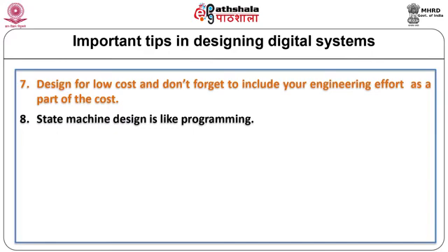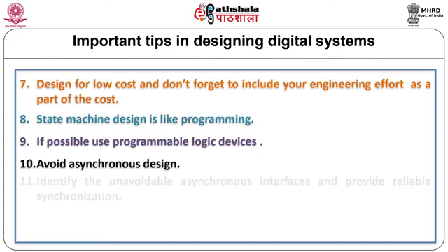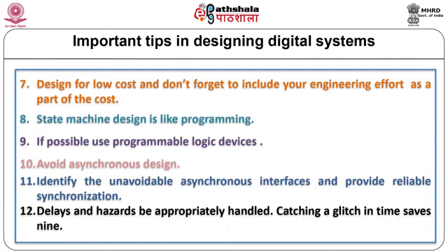State machine design is like programming. Approach it that way. Use programmable logic to simplify designs, reduce cost and accommodate last minute modifications. Avoid asynchronous design. Practice synchronous design until a better methodology comes along. Pinpoint the unavoidable asynchronous interfaces between different subsystems and the outside world and provide reliable synchronization. Delays and hazards must be appropriately handled. Catching a glitch in time saves nine. The above important tips will help the digital system designer to save time, cost and redesigning efforts.